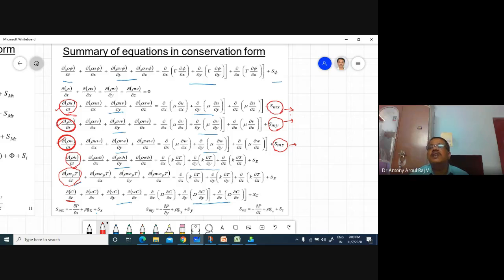You are not going to model the fan. You are not going to mesh the fan. You just have to create a region of fan only. In that you can mention that this much momentum is added in the x direction, this much momentum is given in the y direction, this much momentum is given in the z direction.